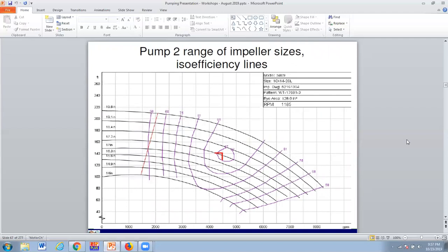Most of the pump curves will indicate the efficiency at any particular operating point. You can read it off of the curve. And so this one's pretty well selected. That's my selection point. This is my highest efficiency ring, and I'm inside of it. So that would be a pretty darn good selection if you can get one like that to work out.